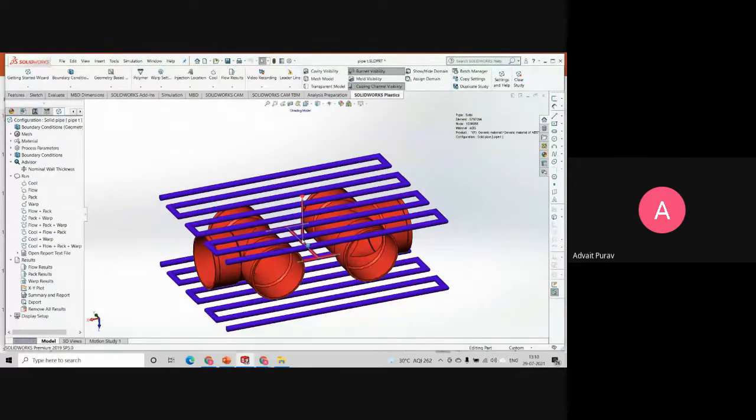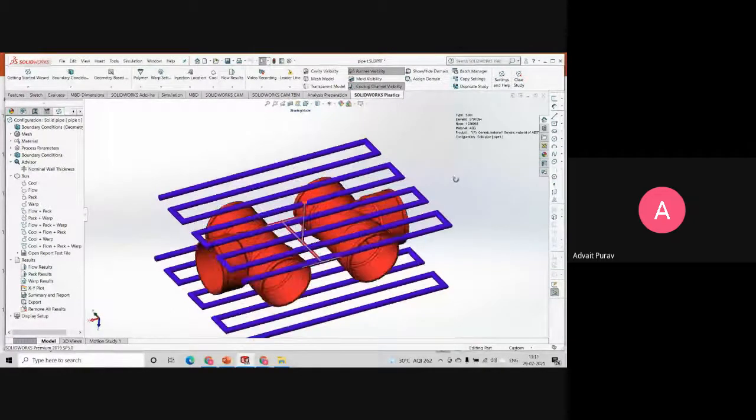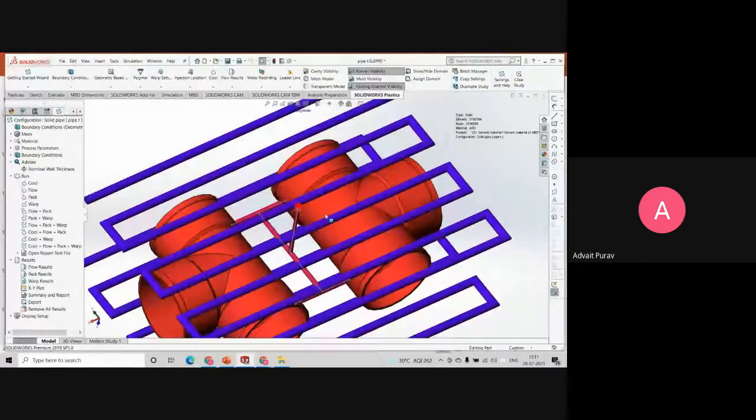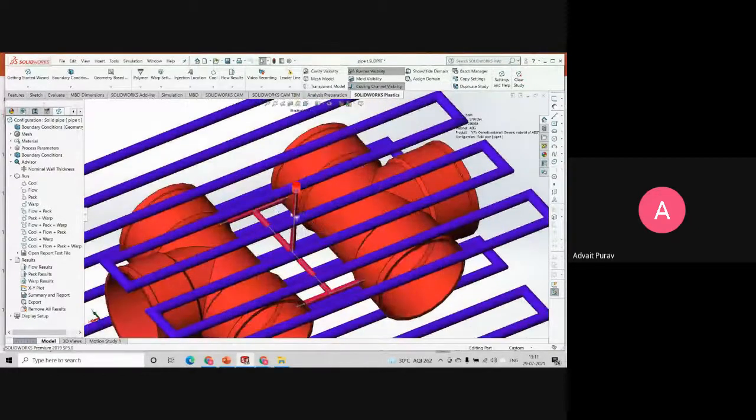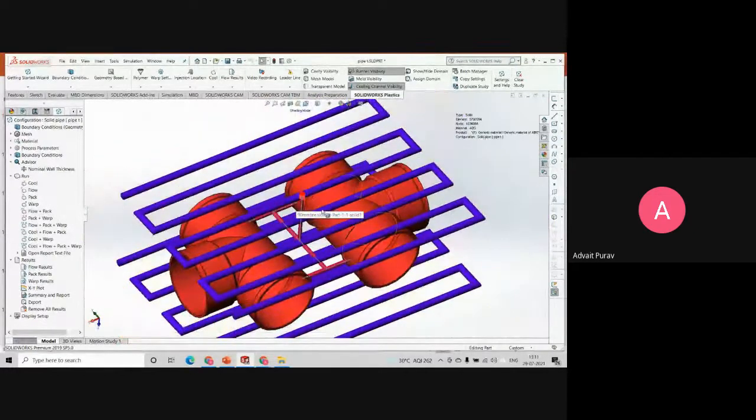As you may have seen in chemistry, when you heat atoms they separate and expand, and when you cool them they come together. But in PP, polypropylene, the molecules remain deformed and extended throughout the branch and don't come together, so warpage increases in polypropylene. So according to the part structure, the part, and the warpage and defects you want to eliminate, you have to choose the plastic wisely. Now suppose bottles, what are they made of?